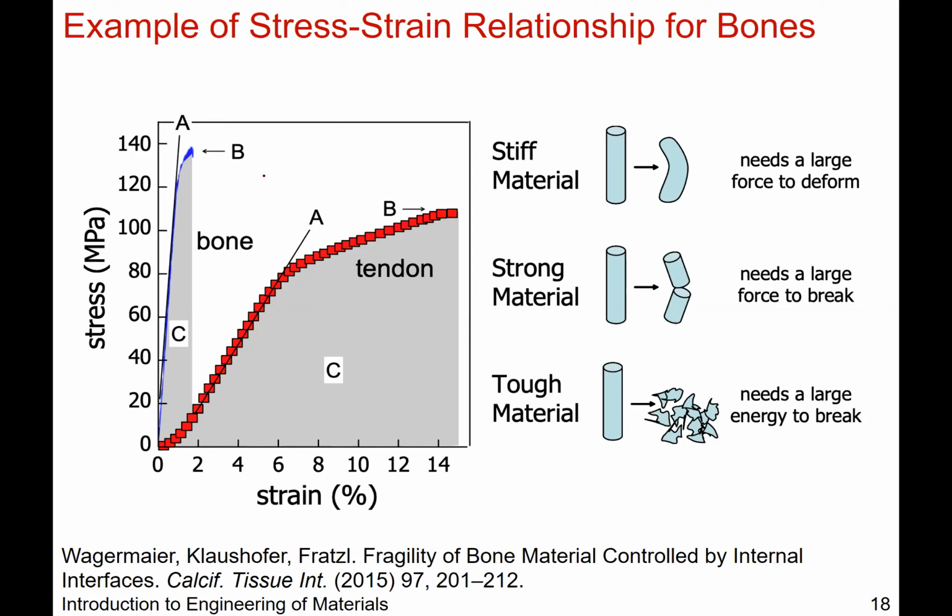So it's a ceramic type material, and you can see here that it's a number of things beyond calcium phosphate. That's the majority, but it's not all calcium phosphate, of course. But basically the point is it's a ceramic type material, so it's stronger, but it's more brittle, right? Whereas tendons, here you see if we estimate the yield strength, and we'll define exactly what the yield strength is, but let's say we eyeball it, and we're not following ASTM convention. Let's say we eyeball it and it's here versus here, right? So bone is stronger, but more brittle.